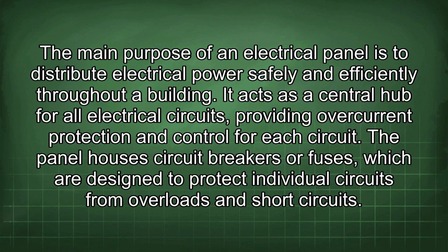The main purpose of an electrical panel is to distribute electrical power safely and efficiently throughout a building. It acts as a central hub for all electrical circuits, providing overcurrent protection and control for each circuit. The panel houses circuit breakers or fuses, which are designed to protect individual circuits from overloads and short circuits.